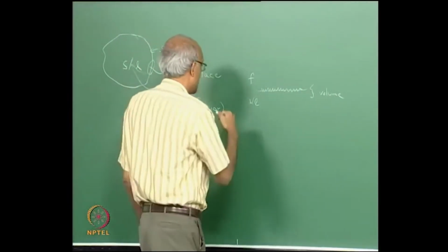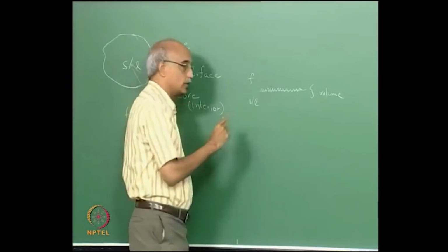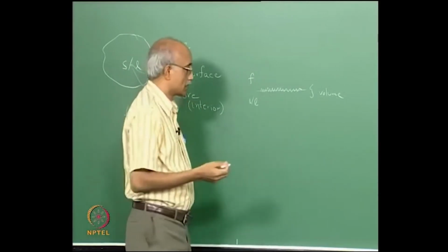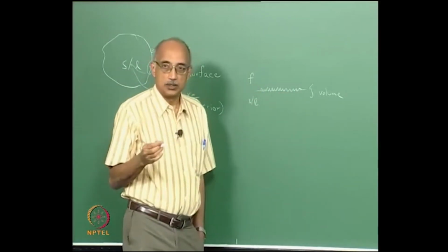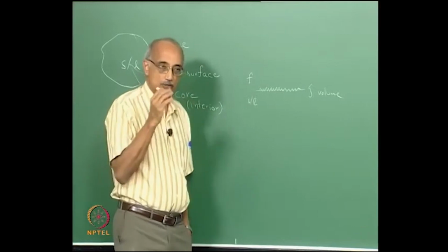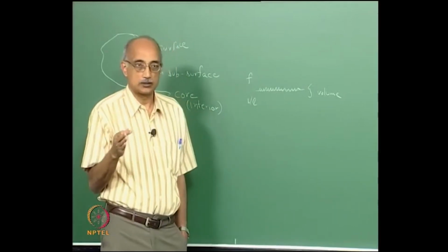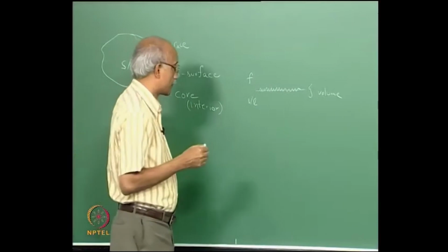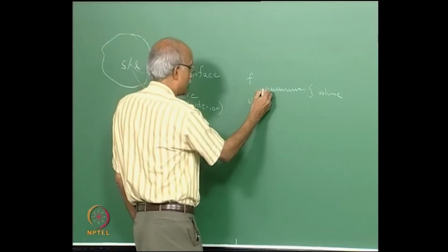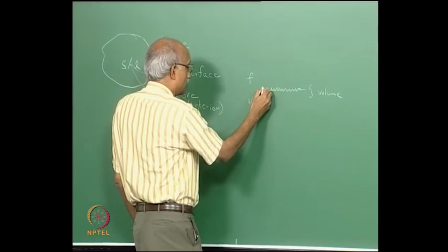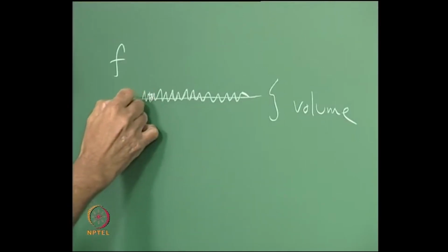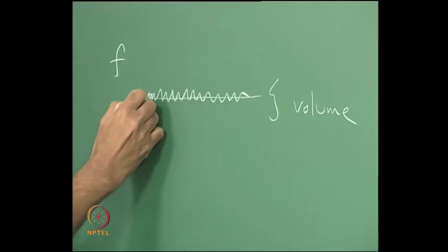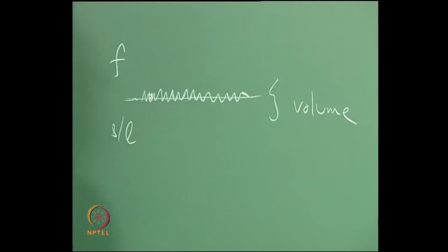So, for example, if you have let us say a liquid that is in contact with the particle, the way that it actually encounters and interfaces with the particle is going to be different depending on the actual location on the surface where the contact or the interaction happens. So, for example, if the liquid contacts this point, it is actually going to try and fill up this asperity, right, whereas if it contacts it on a smoother area, it is going to spread itself differently.